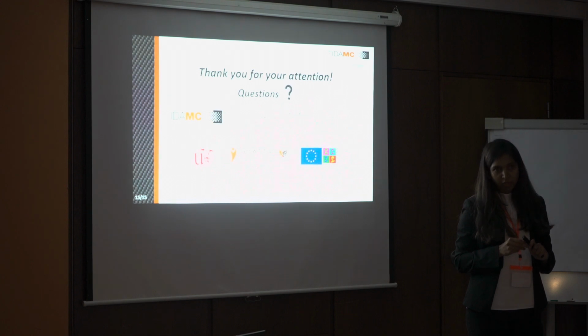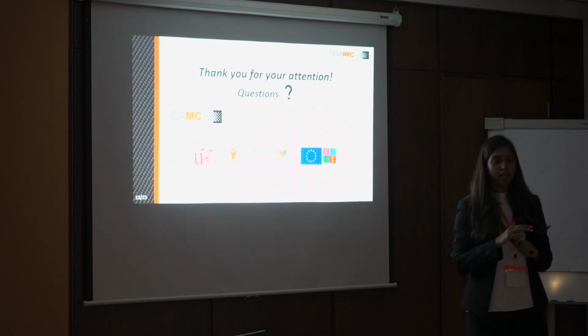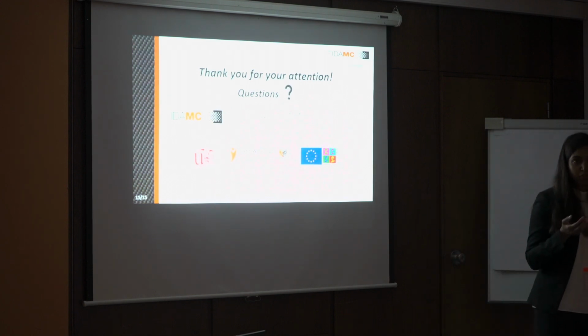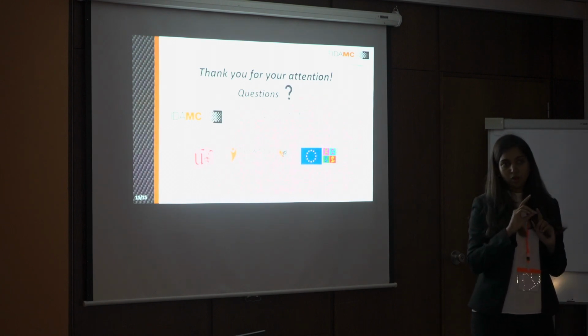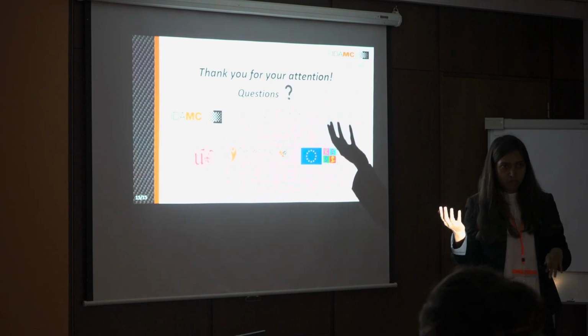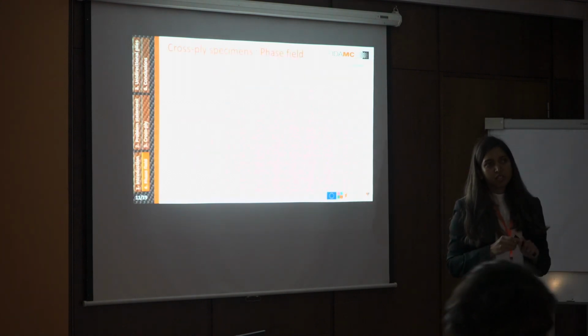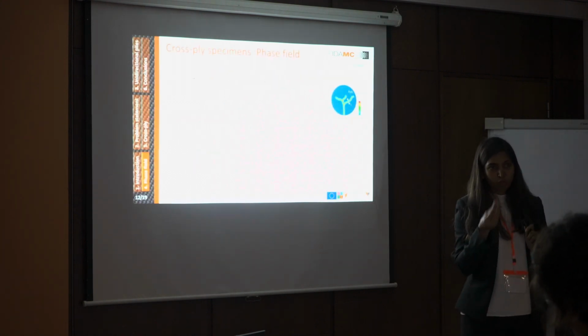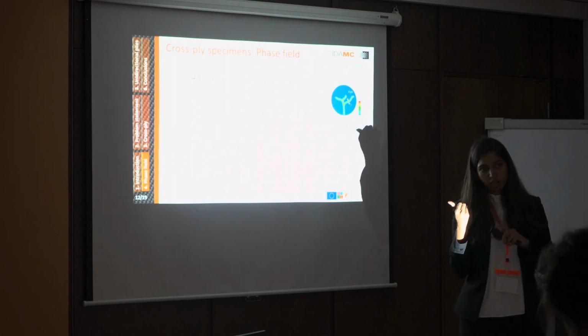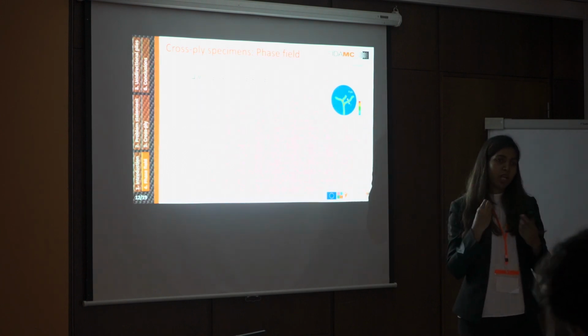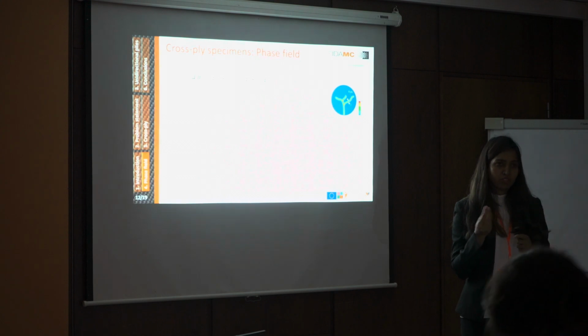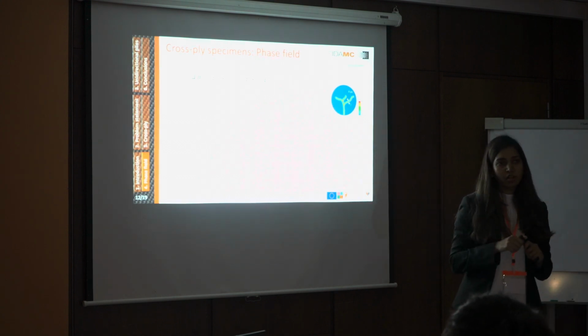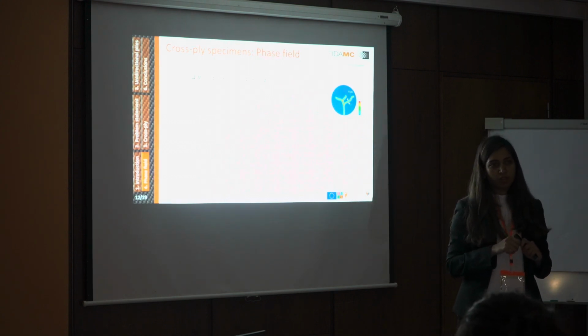It is a tiny value, but as I said, the intralaminar failure may not lead to the final failure, but it is a cause for the final failure, right? So we consider the first non-zero phase field value as our intralaminar failure in the models. And for the analytical calculations, we use a point-wise stress criterion to obtain the intralaminar failure values.